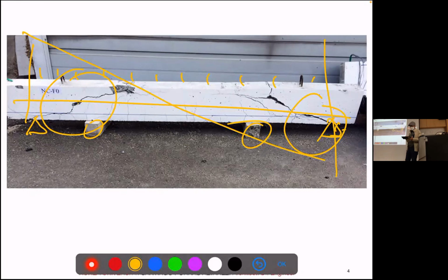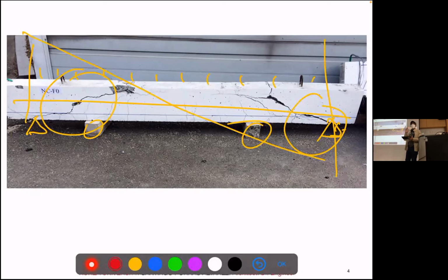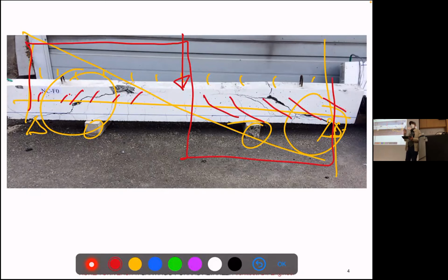But actually, we should change the color. We had a concentrated load, so the graph is simpler, right? That means the stress is the same everywhere. You may have cracks anywhere, because it is exactly the same stress all along, right? That's very easy to understand, and it's better. I prefer that you get the concept of what a shear is and how it happens rather than memorizing those graphs that by themselves are not so meaningful, okay? So let's continue.